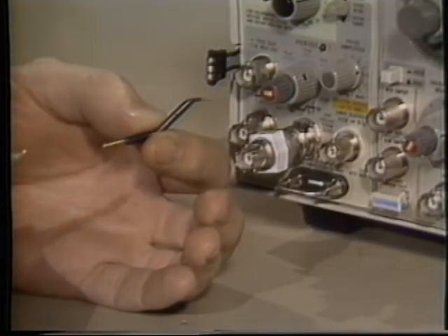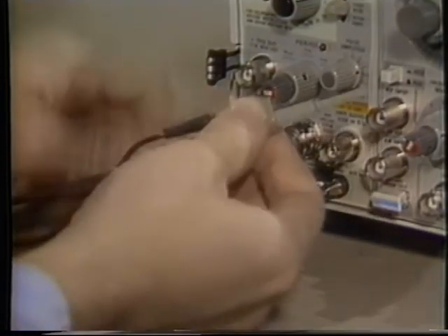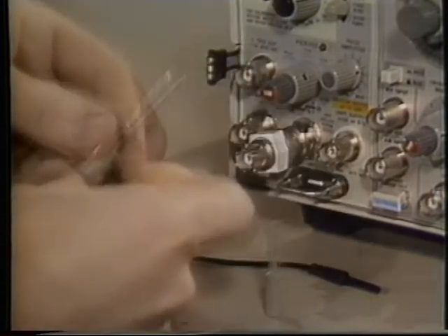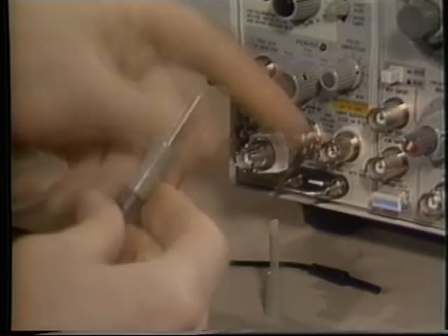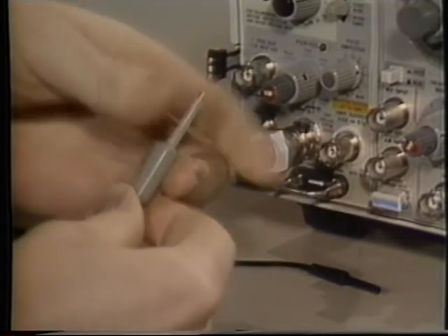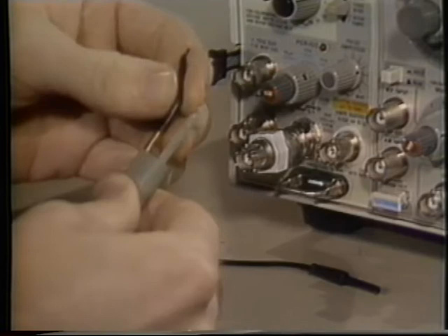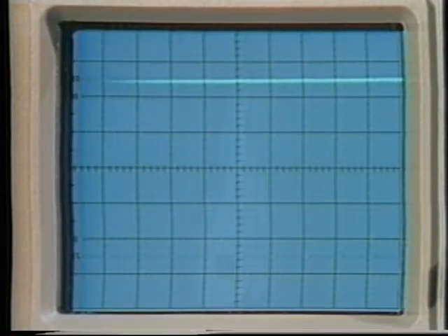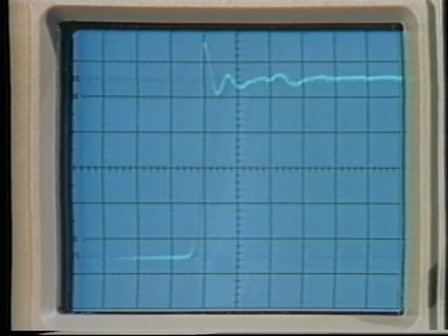But here's a low inductance Z lead. To install it on the probe, unscrew the ribbed tip cover and slide it off the ground collar and lead. Now reverse the ground collar and reinstall the tip cover. Now you can attach the low inductance lead itself. The signal with the Z lead is much closer to ideal. Ground lead inductance falls to 30 nanohenries, which raises the resonant frequency to 267 megahertz, which is much more likely to be outside your area of interest.